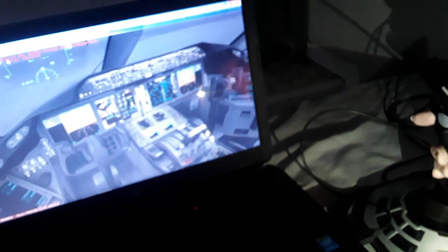So we're gonna take off at about 140 knots, 230, 240, maybe more, 270 kilometers an hour. So we're gonna have 15 degrees of flaps and 9 degrees of pitch attitude for rotation. So you're gonna see we're gonna use the side stick or yoke for pitch attitude in takeoff. We're gonna have also the SIDs, the standard instrument departure waypoints and fixes, the horizontal and vertical navigation fixes, and altitude and airspeed constraints for the initial climb and departure of the aircraft.